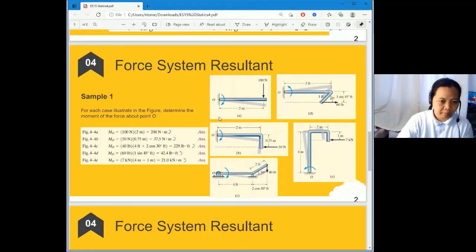This is an isolated case, so you don't need to calculate a resultant, and you don't need a sign convention for this one. You just have to include the direction of the moment. When you're solving moment problems like this, an isolated case, you have to specify the direction, and use our sign convention as discussed earlier if it consists of systems of forces.